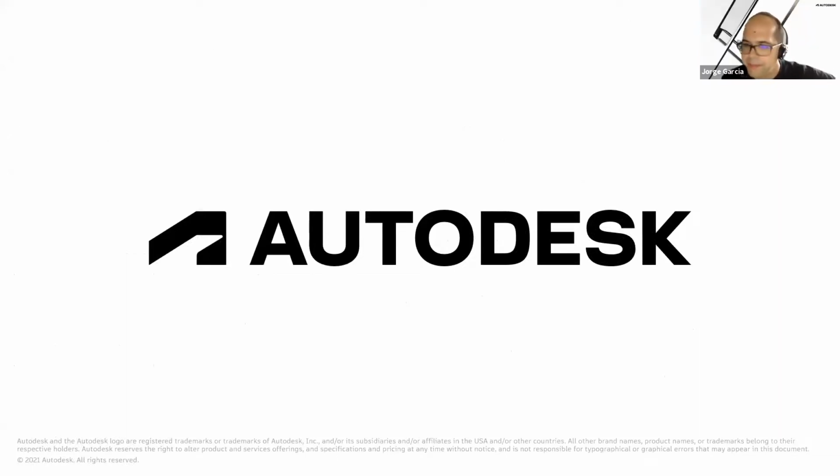Yeah, we do. So the question was, with Fusion, what is the best approach to changing the board outline size and cascading this through the design? Okay, so there's basically one key question here that defines the best approach. Are you using an off-the-shelf enclosure, and that enclosure is going to drive the PCB design? Or are you making a custom PCB and the enclosure is going to be based off of the PCB? Depending on the answer to that question, the best way changes.